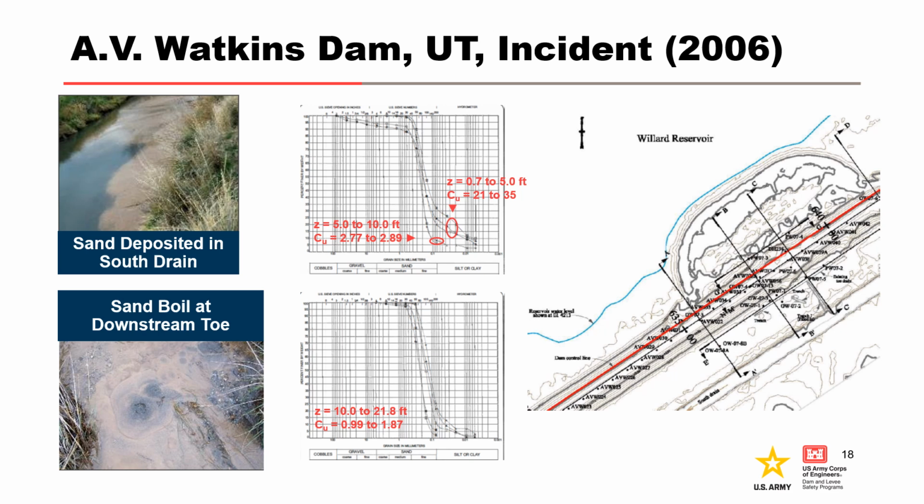The dam nearly failed in the same general area of a seepage incident during initial filling that required installation of a toe drain. Muddy seepage was noticed by a rancher. 140 to 190 gallons per minute was exiting from sand boils.